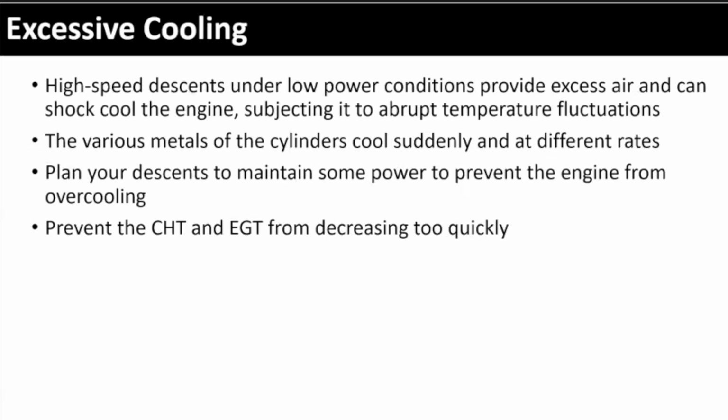Excessive cooling, just like excessive heating, can cause problems in an airplane. It's bad to what we call shock cool an engine. If that engine is hot and all of a sudden is exposed to rapid cooling, that's not good for the components of the engine either. They would call that super cooling or shock cooling, and it can cause problems as well. So when you're doing a steep descent, again, good idea to keep an eye on your gauges.